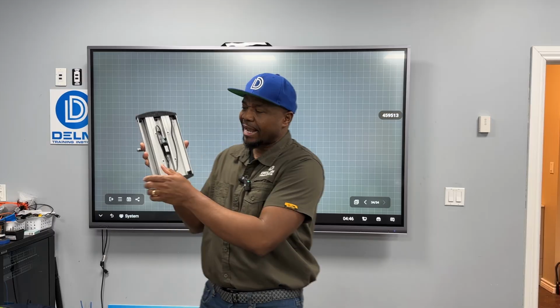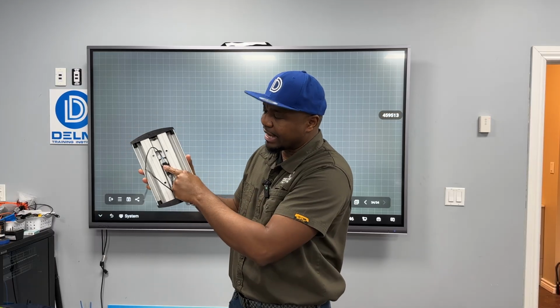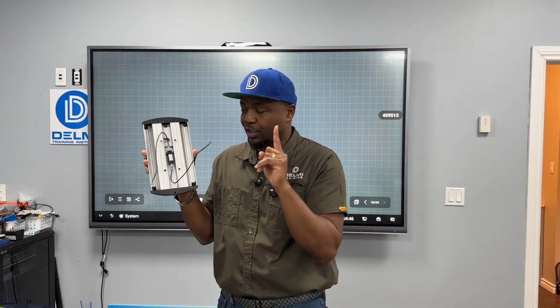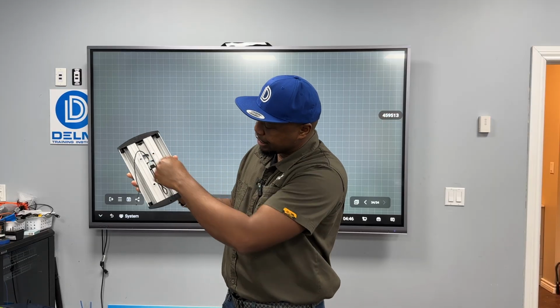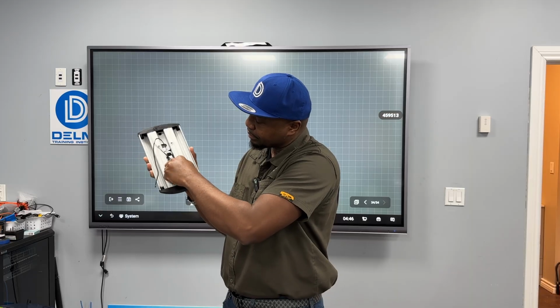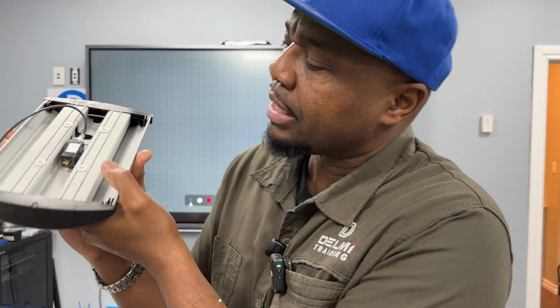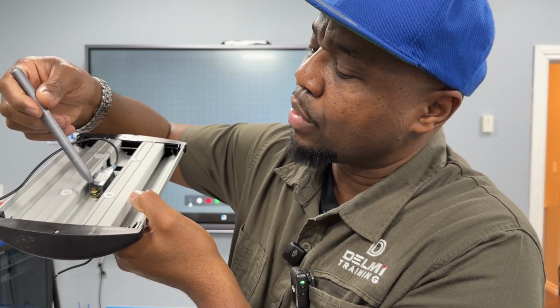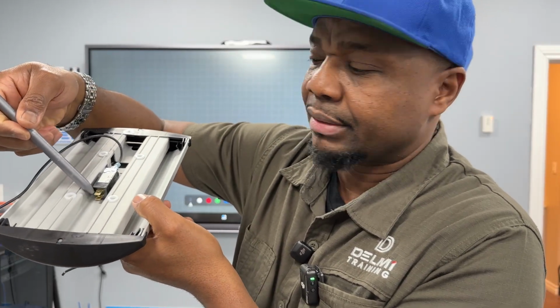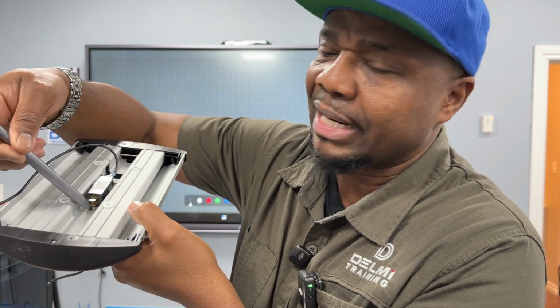When you look on the back, all that you have here based on the manufacturer is a Form C switch. You have the common, you have a normally open, and when I take this pigtail out, you see there are 2 terminals here, one here and one underneath it.